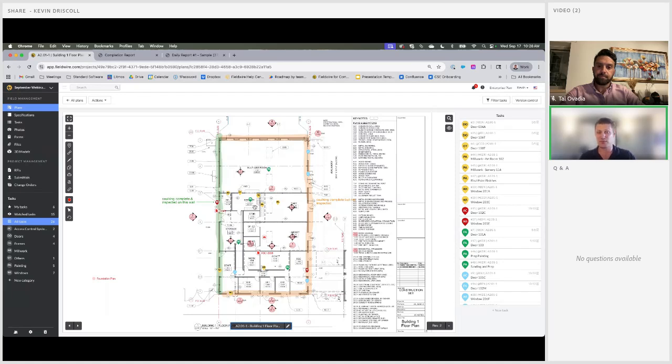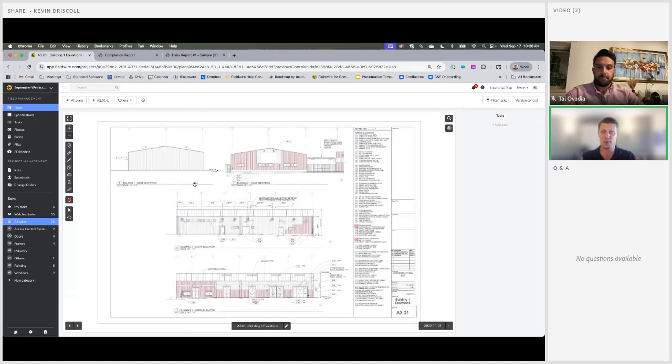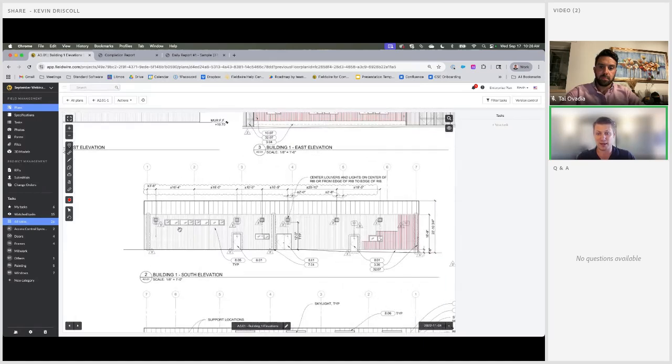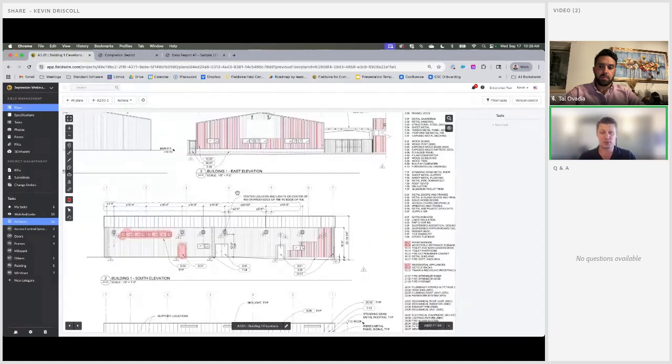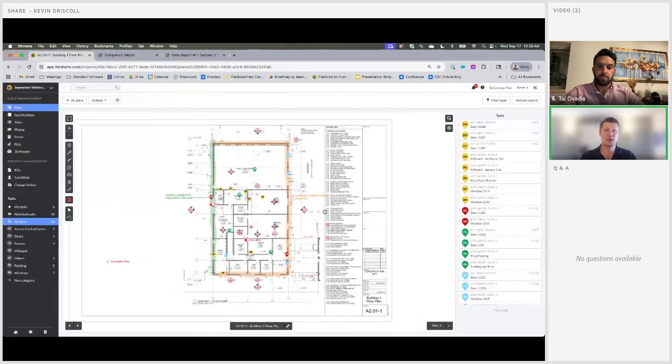So for example, if I'm a window subcontractor and I want to view this elevation view to do some sort of window takeoff, I can just pop into this hyperlink that Fieldwire has created automatically and begin to do my window takeoff, maybe make some notes, some highlights, all of that directly on the page here with that breadcrumb back to my original plan set. So it makes that plan viewing experience really nice and seamless, organizing your drawing sets there.